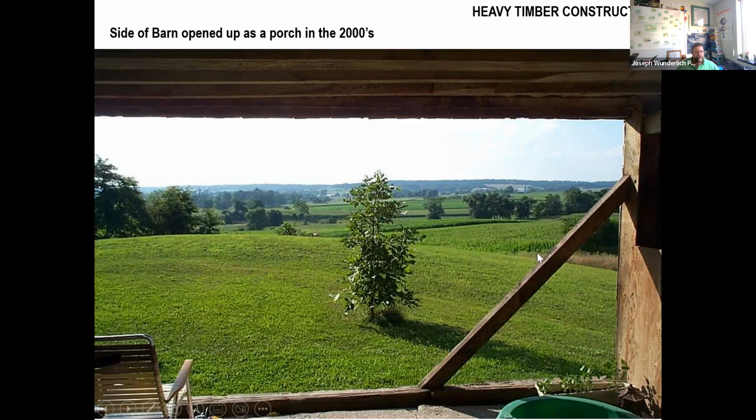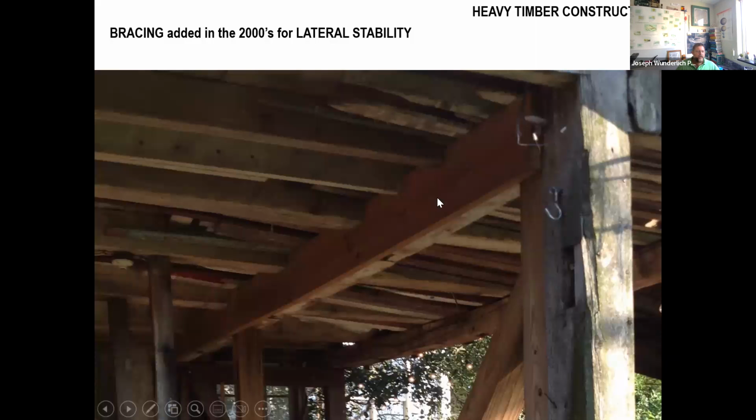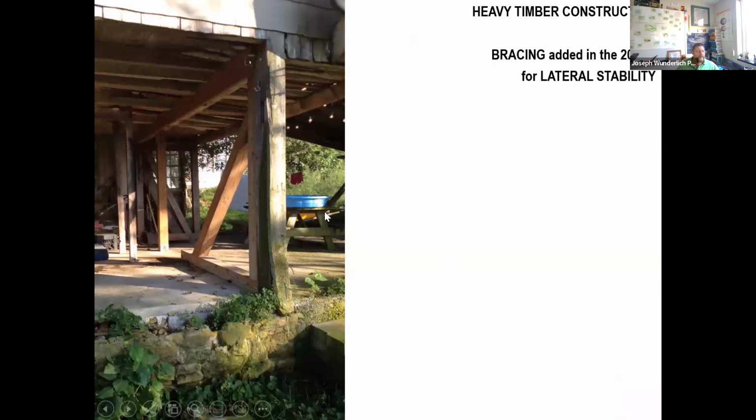And so this is heavy timber construction. This is mortise and tenon. This is a lateral diagonal strut for holding up the building against wind loads. And then you'll see I've put more in recently. I'll go into details of that. And bracing added in 2000s for lateral stability. And you can see that here.